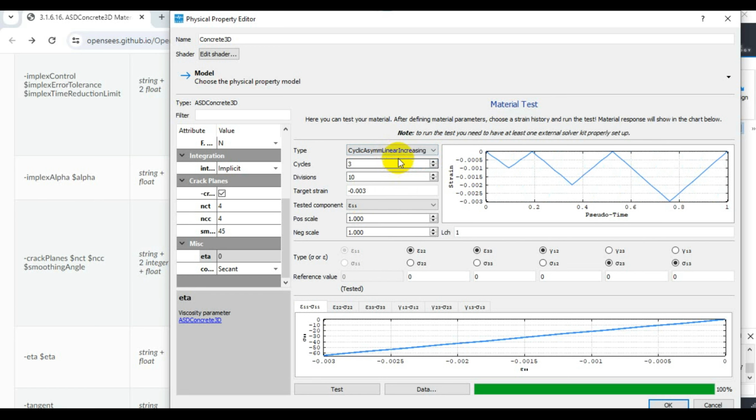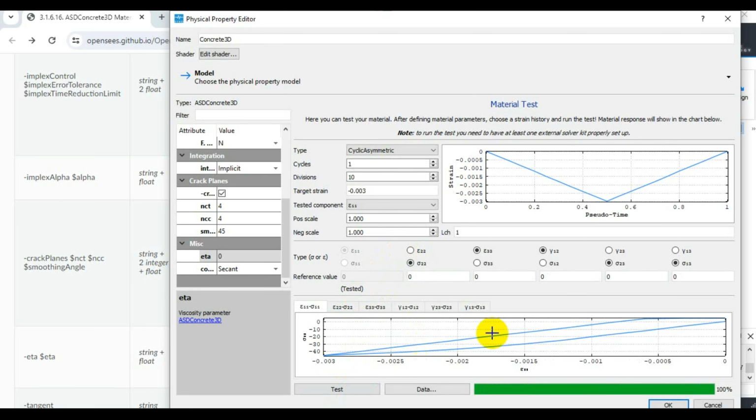So let's say I converted it to, you can then look into these parameters here. This is for strain 11 and stress 11 direction. Let's switch to this direction, and then we should select for this the strain direction as well to check the behavior of the materials here.